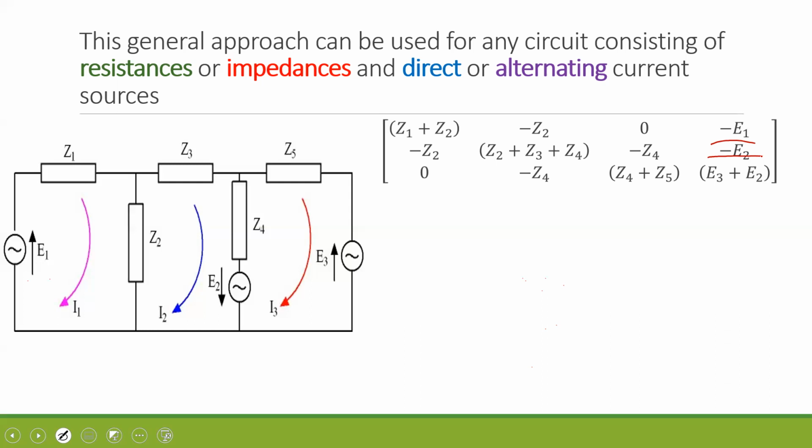Sir, the two of them? Which terminal is I3 entering? Negative. Stop guessing. Look at the circuit. If it's entering the negative for 1 and 2, and it's coming at the bottom of the arrow, does I3 look like it's coming into the bottom of the arrow?